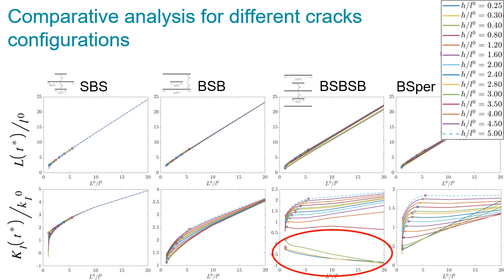These figures show the relative length and the mode 1 stress intensity factors at the tips of the big cracks closest to the center in two configurations, with 3 cracks, one with 5 cracks, and in infinite configuration, the last one, after 150 hours of the crack's growth.